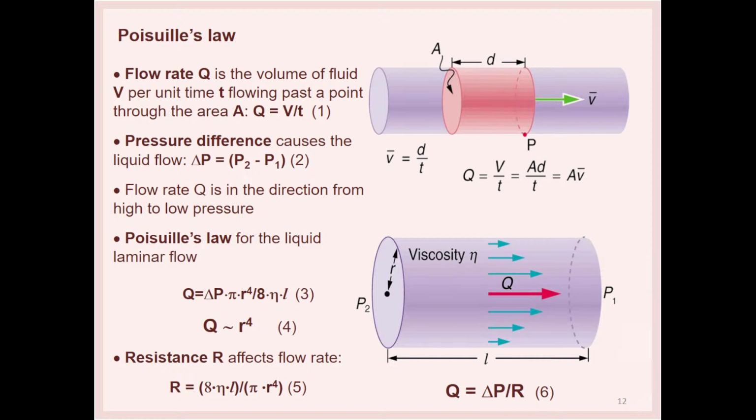A technique called dimensional analysis shows the relation of the parameters mentioned, which can be written as the equation under number 3. The formula for the flow rate is called Poiseuille's law. Poiseuille's law is valid for straight rigid tubes that contain a fluid with constant flow rate and constant viscosity. Therefore, it is not strictly accurate in regard to the human vascular system. Nevertheless, important principles relating flow and tube parameters remain applicable.